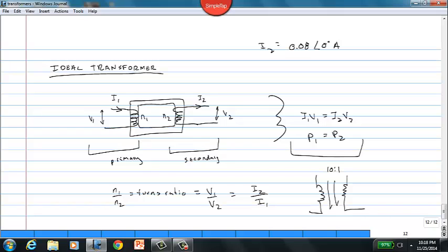So this is what is meant by the ideal transformer, and the simplification we'll use is that power is constant, ignoring the resistances and such things, and assuming that all magnetic flux from N1 is coupled into N2. What we find is that all we need to know is the turns ratio. We can ignore all the losses due to the self-inductance, mutual inductance, and parasitic resistances. So that's what we're going to start working with, because this transformer model using the turns ratio is really what's most commonly applied in electric power systems. And this really is a pretty easy application.